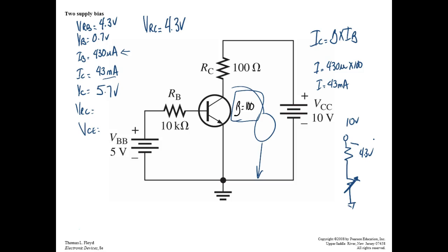And that's what's very important about that voltage collector to emitter. We can tell right off the bat what region that transistor is operating in. So if it's operating in saturation and it's supposed to be operating in the active region, then we can figure out what the problem is real fast. A lot of times to troubleshoot a transistor, if we know what these bias voltages are supposed to be, then if they're not what they're supposed to be, something's wrong. And then from those measurements, believe it or not, it's not very complicated to figure out what's going on.